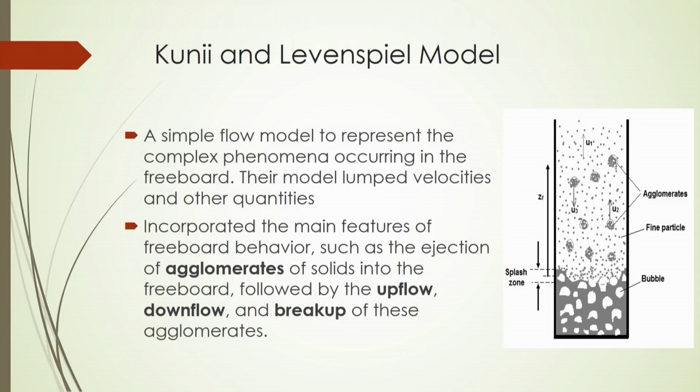So, these are the agglomerates inside the bed they have considered here, and whenever the solid particles move upward by the entrainment mechanism, these are the agglomerates, and these white portions are called bubbles. So, bubbles are coming from the bottom, and the black or ash color is the solid particles. Due to the breakup of the bubbles at the surface by ejection, the solid particles will be thrown to the top, and it will be entrained.